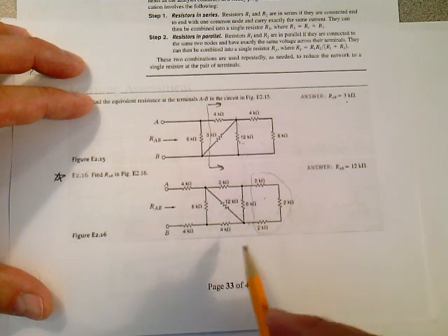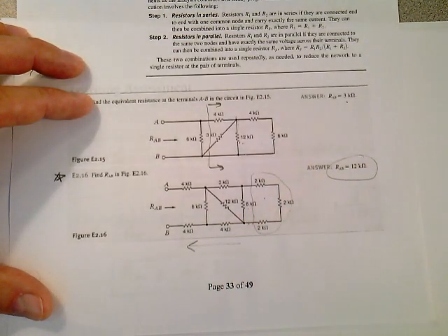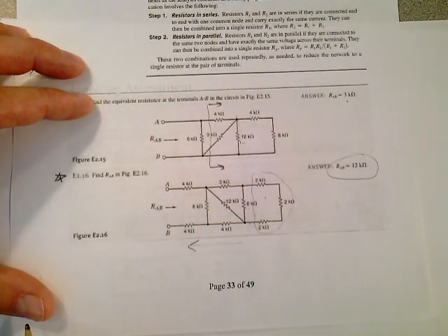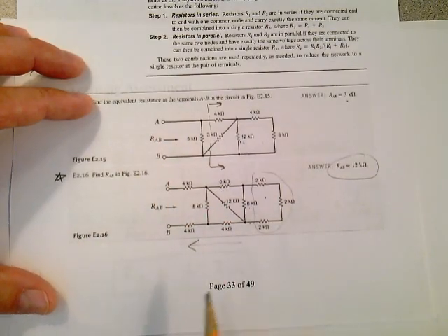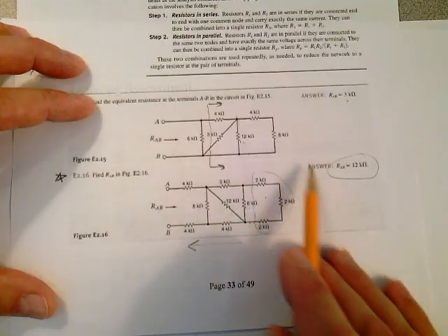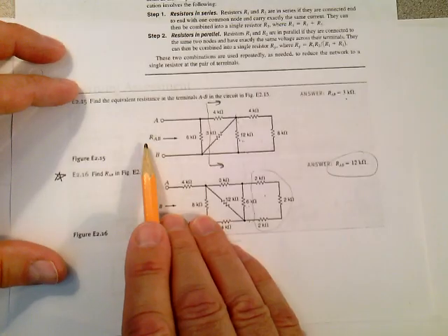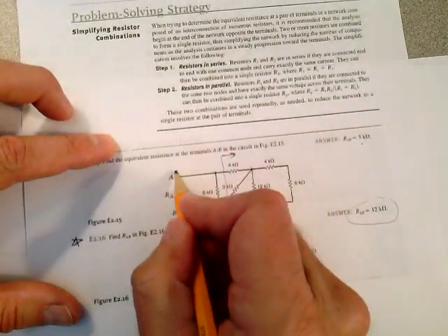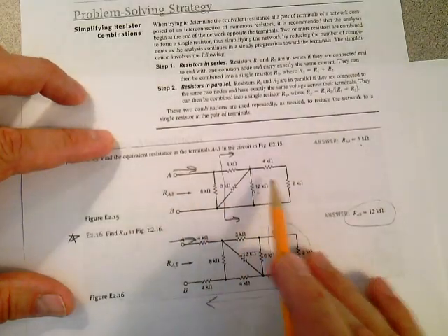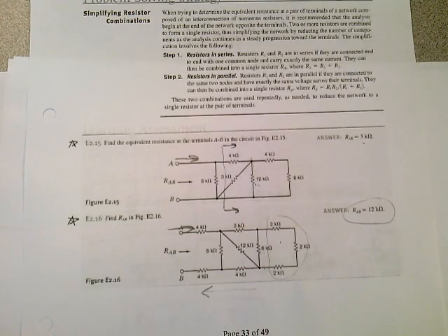And you can work this backwards, and you can see you get 12K ohms looking in from the left. Up here, you get the 3K looking in from the left. And why are we trying to find these total resistances in these circuits? Because once we know the total voltage, we can divide by the total resistance and get the total current coming in there, or the total current coming in there. And then we can find these different branch currents. That's the next lecture. That concludes this lecture.